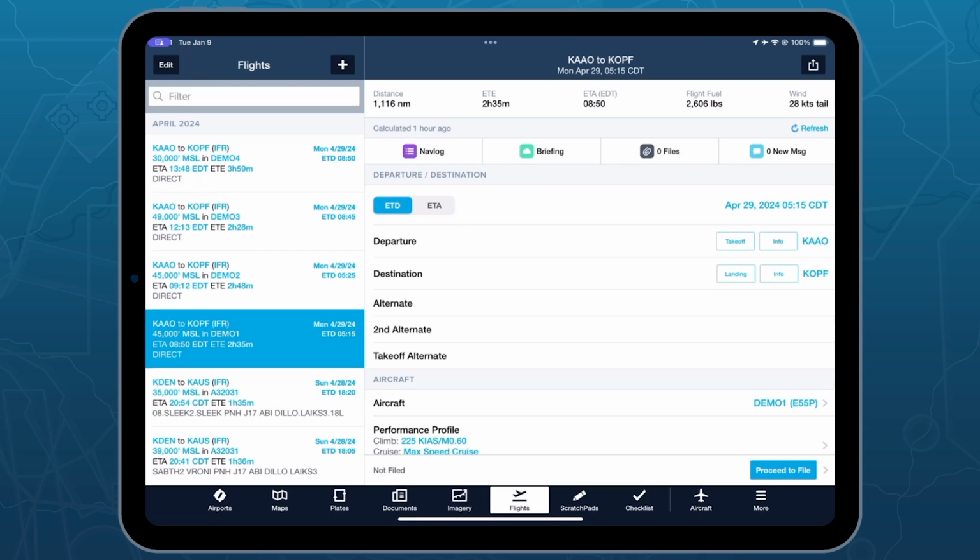The choice of a runway selection with a landing factor can be confusing to pilots. This is not surprising given that these selections are often a function of the aircraft's available published performance data, the certification basis of that aircraft, and the type of flight operation itself, such as Part 91, 91K, 135, or 125 operations. Michael and I are going to work through 4 different examples showing how our updated landing factor workflow provides a pilot the framework to help with selecting the correct landing factor and runway surface condition. Before we get to the examples, though, Michael is going to briefly mention a few references and resources worth reading on this topic. Thank you, Jordan.